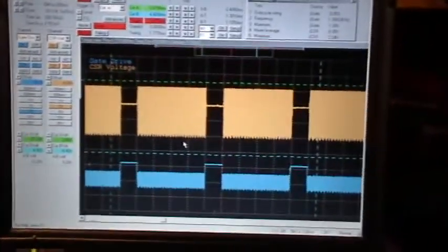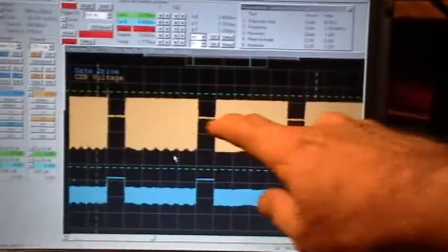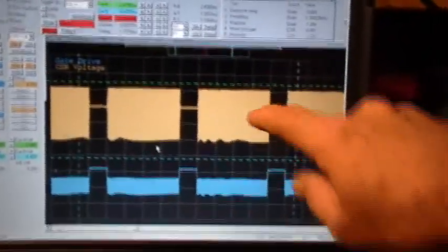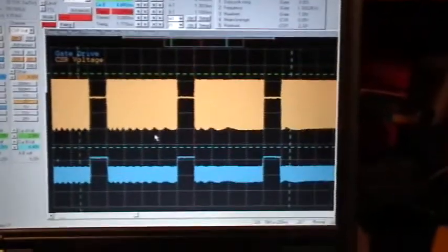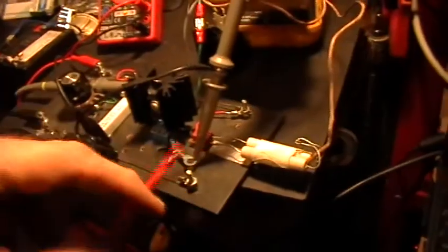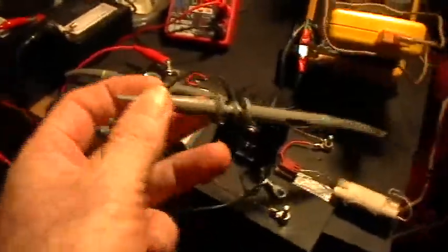Okay, so now I have the oscillation set. This is a typical behavior mode here, no current in this portion, nice oscillations. So now let's see what the true open circuit voltage is of the function generator. How do we do that? Well, we simply go over here to the circuit, we disconnect the positive probe from the circuit, and we disconnect the scope probe that's making that measurement. And then we hook those together.